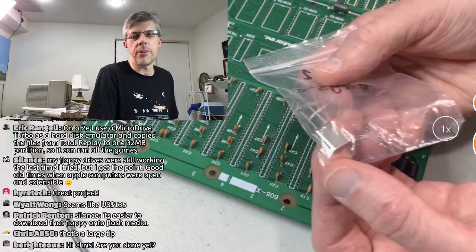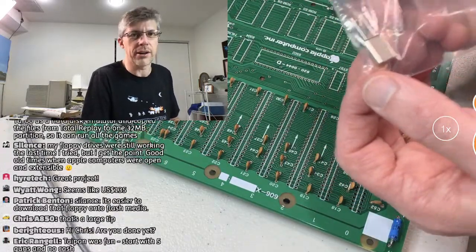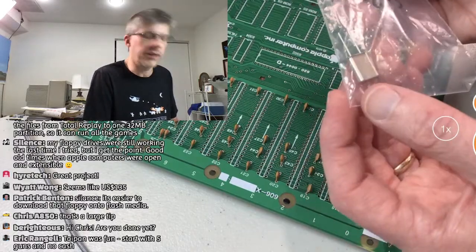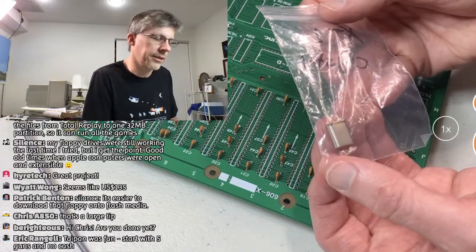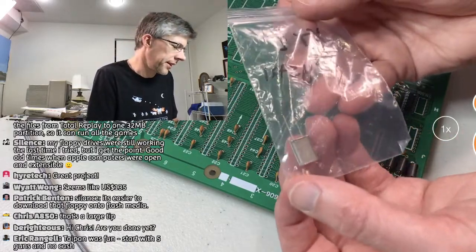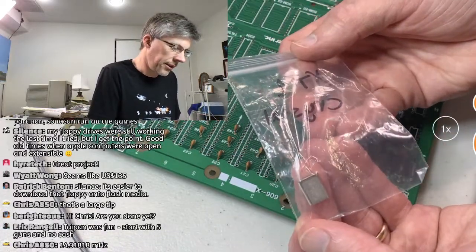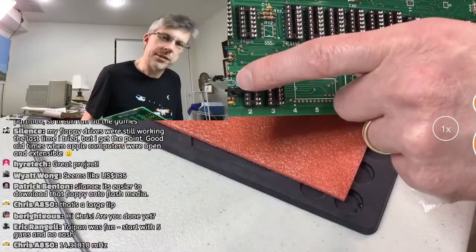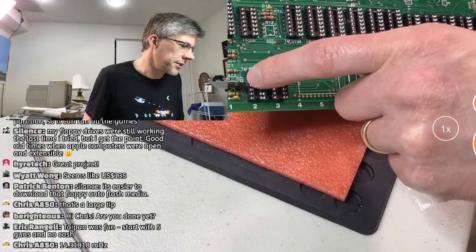14.31818. So if you remember, the Apple II runs at 1 megahertz, but things like the video signal need higher frequencies, typically like 7 megahertz, and there's something else that's 3 megahertz. So basically you use the 14 megahertz crystal, which goes in the board, and then down here it gets split up into a whole bunch of different signals, each with its own frequency.